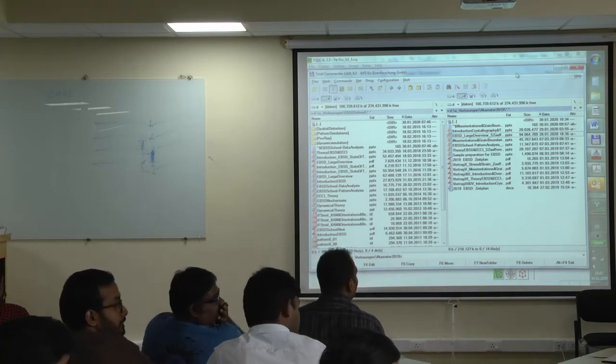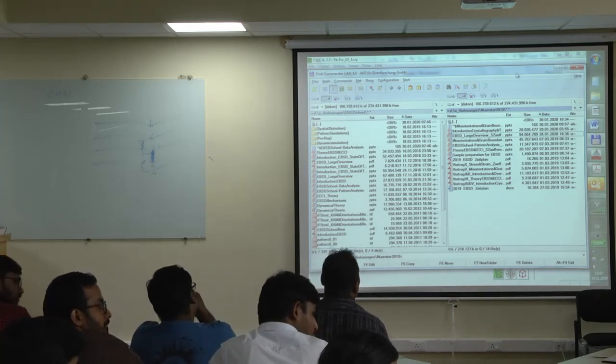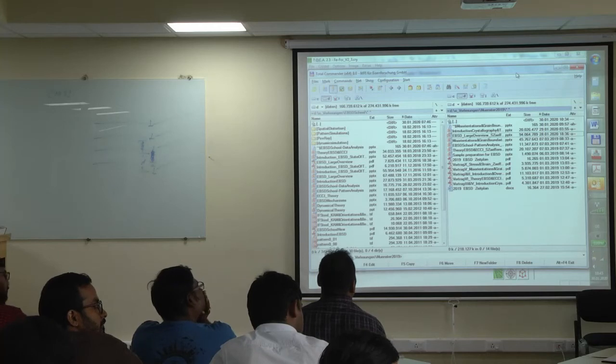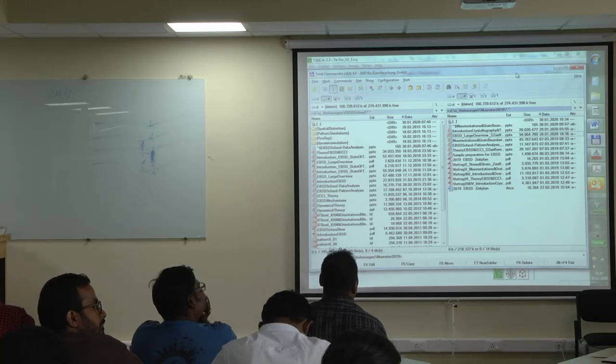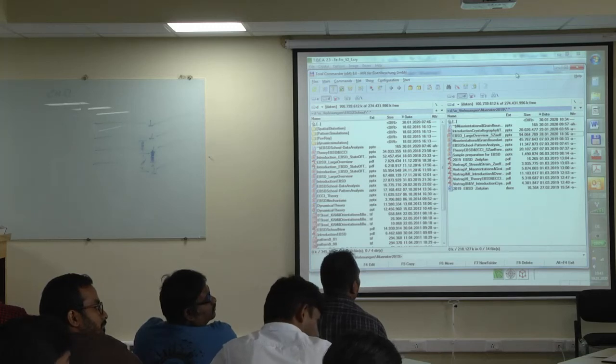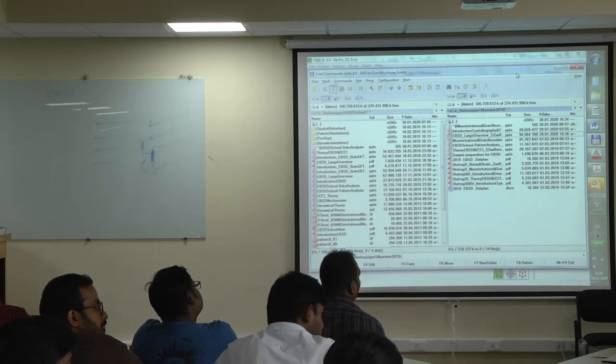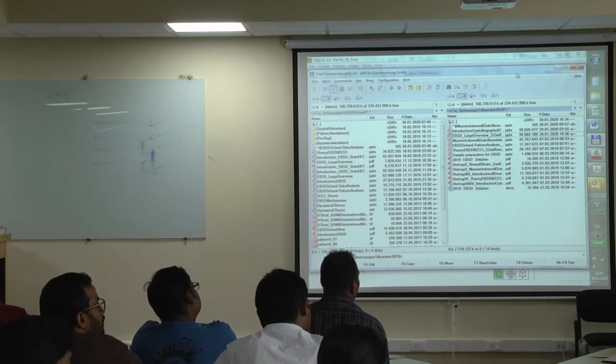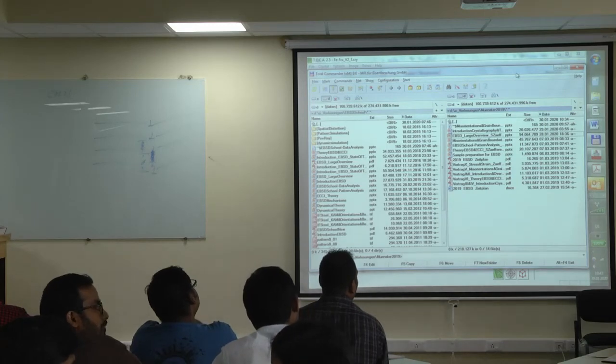So looking at the disorientation angle, sigma 3, 60 degrees. It seems that based on the Read-Shockley model for dislocations, for the low angle to the high angle boundaries, we put the limit at 15 degrees, right? But now, 60 degrees. Is there any dislocation model which can explain this sigma 3? Good question. There's no way.